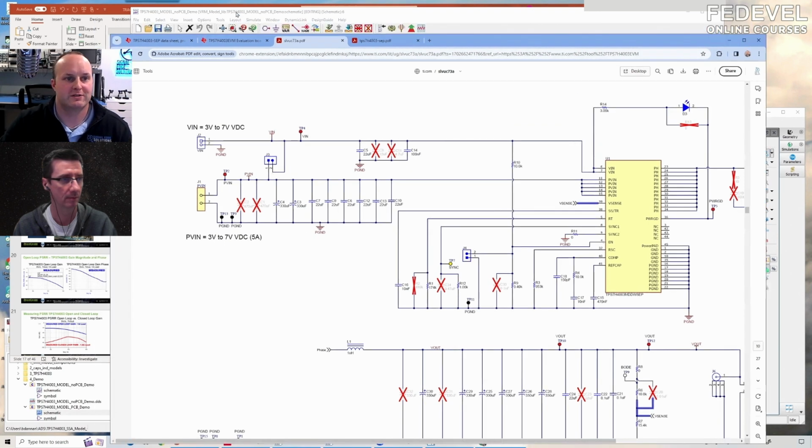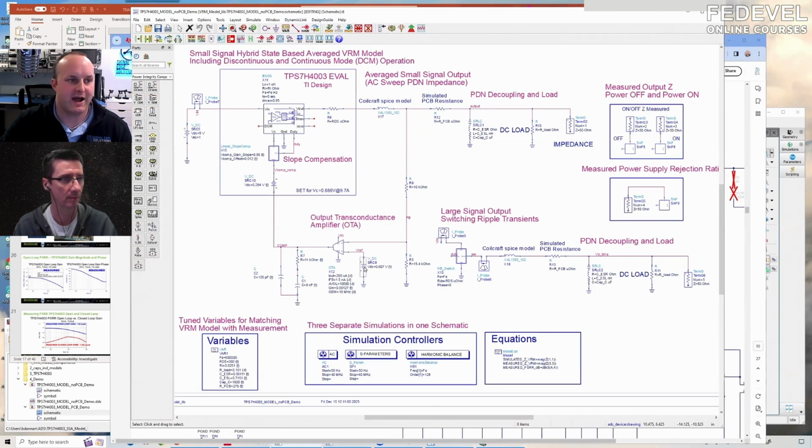So you tune these to match, so you get your response to match from measurement on what's installed. There is some adjustment you may have to do here to get your overall response, but you could just put in the ideal numbers, the nominal: 10K, 10 nano, and 150 pF if you wanted to.